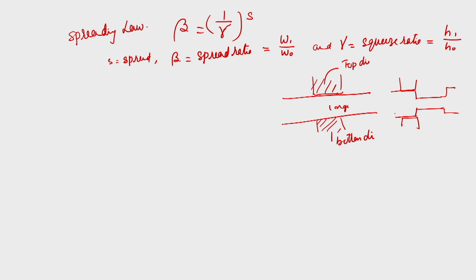If the deformation is very large, the metal will flow and you will end up with a lap. The metal will come over that, so there is an overlapping. That is why it is called a surface lap. At the unforged portion of the workpiece, if the deformation is too large, it will be like shearing and a step is formed. When the next one comes, metal will flow here and you will have a lap in this region. That is undesirable.